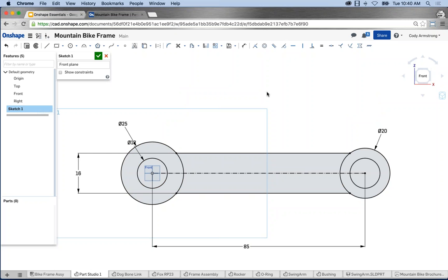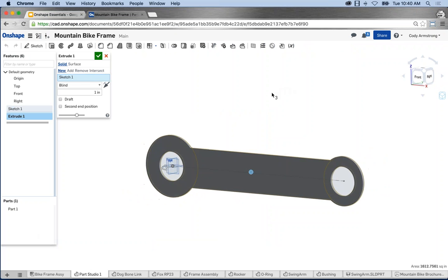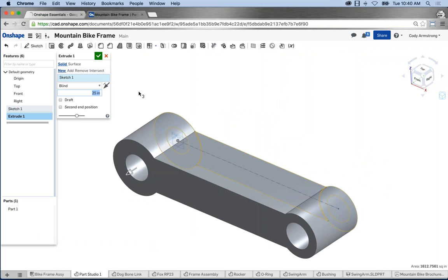Notice that with Onshape, I'm not really concerned about making sure to trim entities out so I have one closed contour or any of those kinds of things. With Onshape, I can extrude the entire sketch, including overlapping contours or any piece of the sketch in the extrude command. So you'll see the extrude command in the top left corner here. I click extrude. We'll rotate the model a bit. Okay. I punch in my depth. I have options to create a symmetric extrude, up to face, up to part and so on. So you have end condition options.